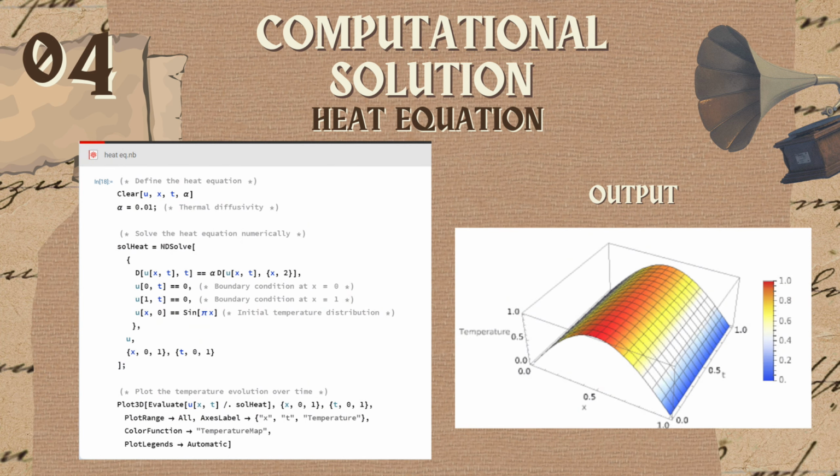For the boundary conditions, I ensure that temperature is 0 at the ends of the domain, which is x equal to 0 and x equal to 1. For the initial condition, I assume a sinusoidal temperature distribution, meaning that the heat starts concentrated in the middle. Finally, I use the mathematical functions to numerically solve this equation over time.